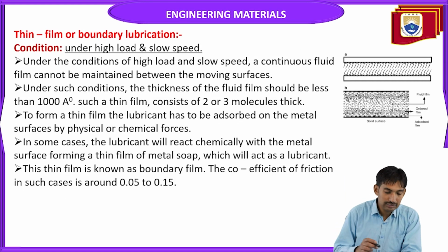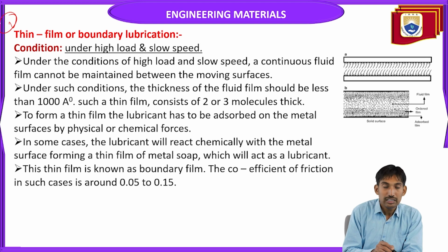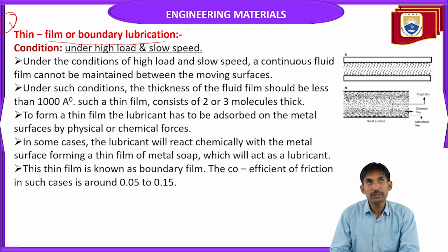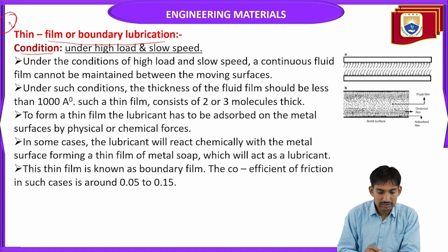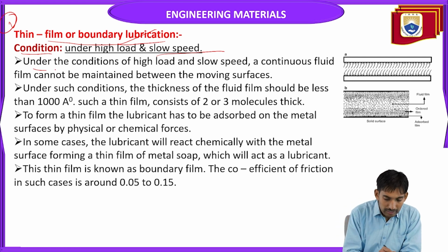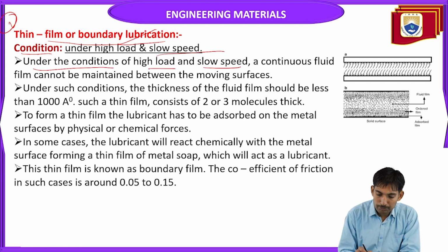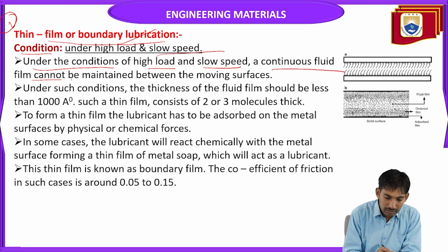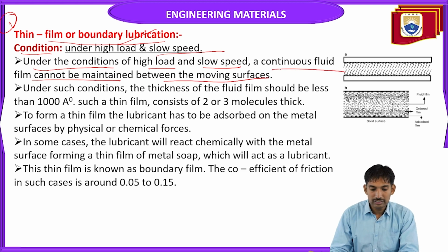The second mechanism is thin film or boundary lubrication. The condition in this case is under high load and slow speed. Under the conditions of high load and slow speed, a continuous fluid film cannot be maintained between the moving surfaces.